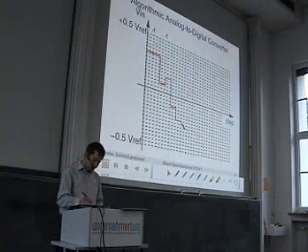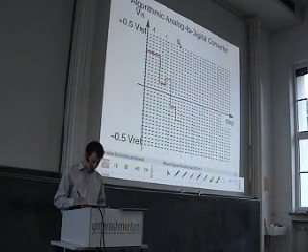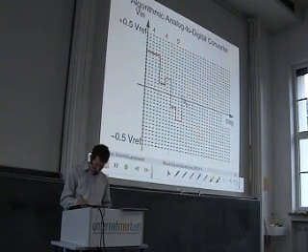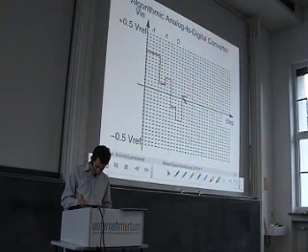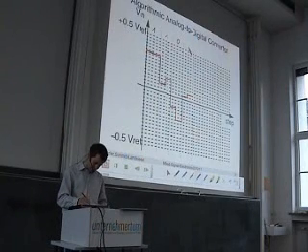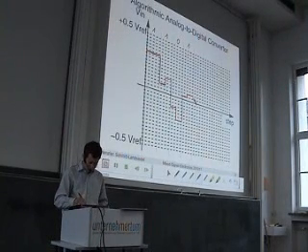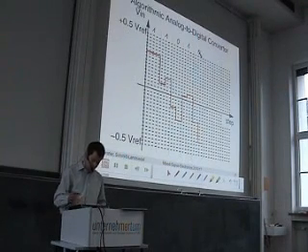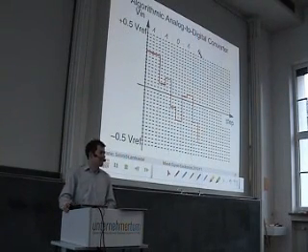This one is negative, so we set the bit to 0. We increment it by Vref over 4, get this new error voltage, and we have to double it. Now we are positive again, set it to 1, subtract Vref over 4, double it, see that it is negative, and so on and so on.